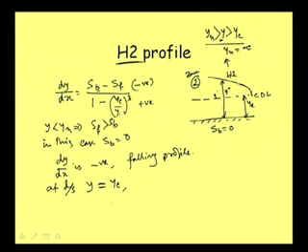Now, if y becomes equal to yc, then the denominator term, yc by y, is becoming 1, and this term becomes 0. So, dy/dx becomes infinity. That we did discuss in our last class several times, that dy/dx is equal to infinity.